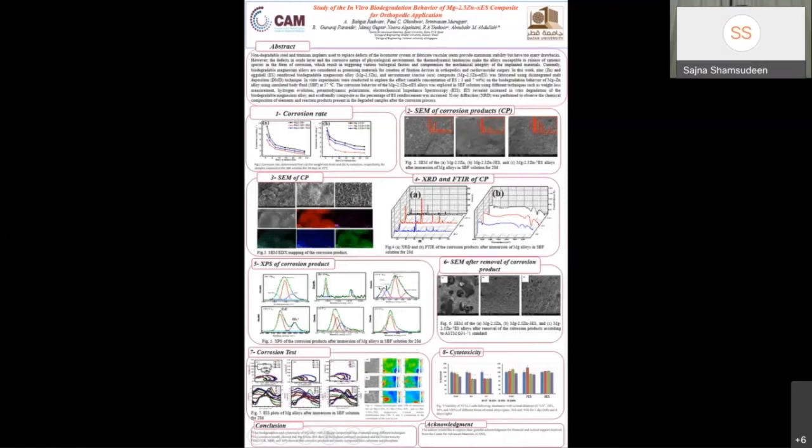So magnesium alloys have been employed as biodegradable material because their mechanical properties are relatively close to natural bone, and in order to avoid the second surgery. However, the main problem of magnesium alloys is their high corrosion rate, which can severely affect the mechanical properties and the integrity during tissue healing. The failure of the implants is in the range of 70 to 89%. Crevice corrosion is the dominant degradation mode of failure, at 86%.